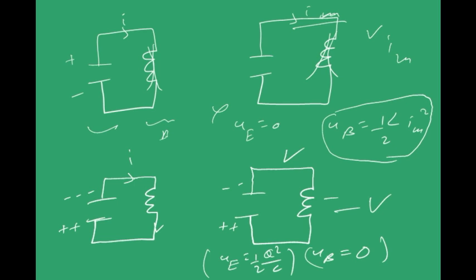And these oscillations are similar to the mechanical oscillations which you have in the case of a spring. Say you had a spring here and a mass attached to it. When you disturb this mass, what happens? This mass oscillates in this way. And throughout this motion, the energy is just transferred from kinetic energy to potential energy and potential energy to kinetic energy. It is something analogous to this situation. For a perfect LC oscillator, the energy is just oscillating between capacitor and inductor forever. But for a practical case, these oscillations die after some time.